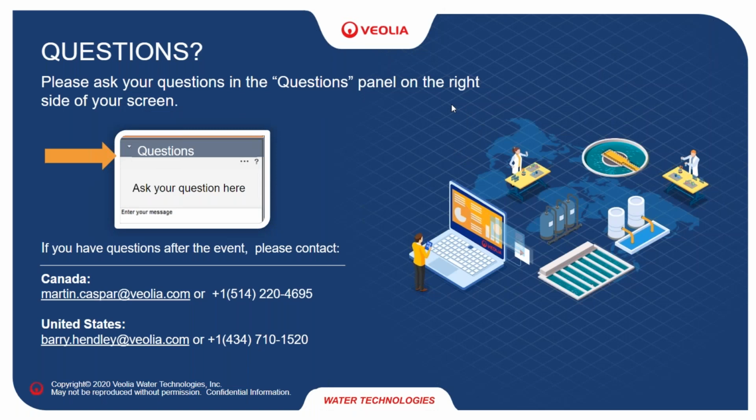Question: if the coagulation mixer was to fail, could we still operate the Actiflo? So I'll take this as best I can. Yes. Typically, that's one of the 2 mixers, and it's clearly not optimal, and it depends on how much contact time you have with your coagulant or whatever reagent. It is upstream. So as far as your functional description is concerned, the answer would be yes, but you probably have to compensate in some way.